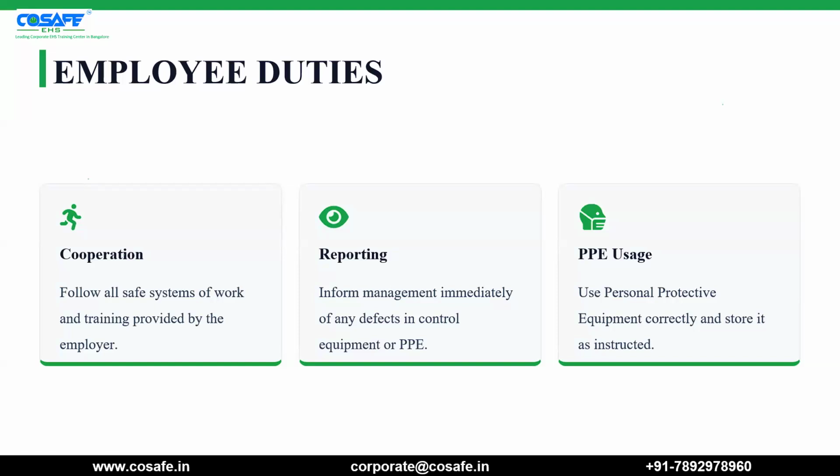As I've seen on many sites, whenever the worker is given a helmet, they won't fasten the chin strap. Whenever he has been given a mask, he'll wear it partially, keeping his nose exposed. Those are not the proper way. Sometimes it might be due to administrative issues, that they haven't been trained properly or informed how to use it.